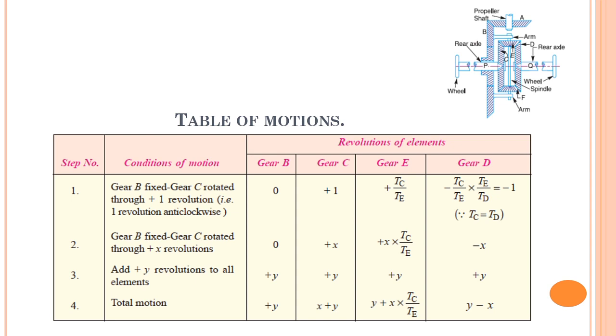That's why for a gear which is horizontally placed like gear E, I will always assume the sign for rotation as a plus, whatever its meshing gear's sign is. Therefore when gear C is rotating with plus sign, gear E I have considered also rotating with the plus sign. And if E is rotating with plus, D I have considered with a minus sign, because it is a vertical gear having its axis horizontal, not a vertical axis, isn't it? This is the first condition. Apply the second condition.